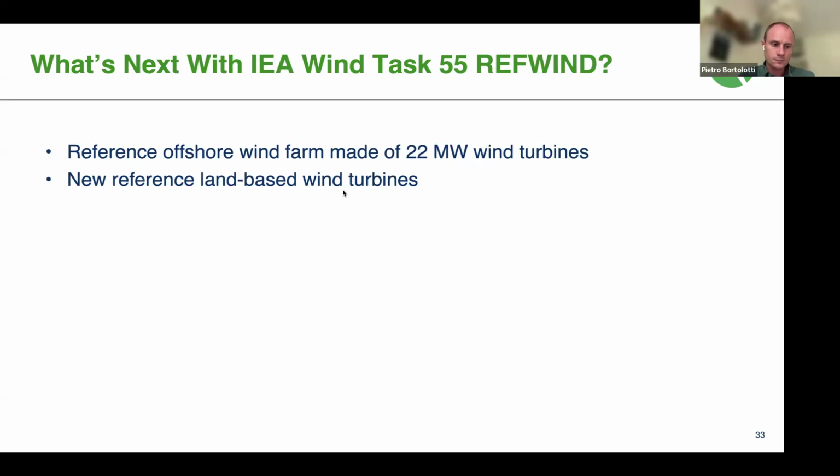They are kept constant, but we optimize the thickness of each of these materials in the different areas of the blade: spar cap, leading edge reinforcement, trailing edge reinforcement. But others are kept constant. For example, the skin laminates are kept constant during the optimization. Otherwise, it's a fairly low fidelity structural representation.